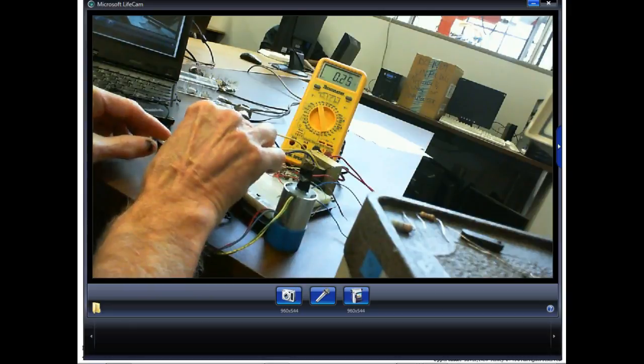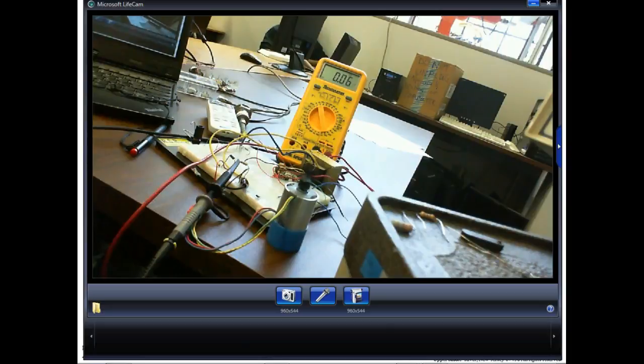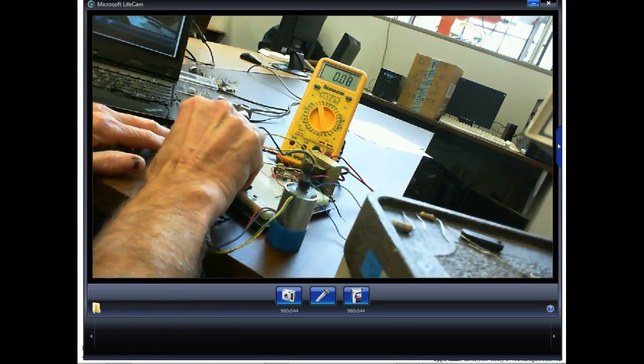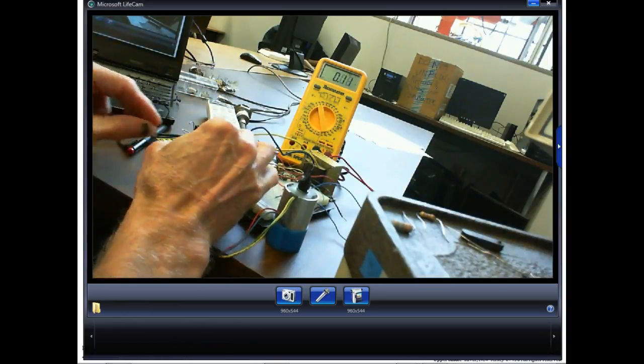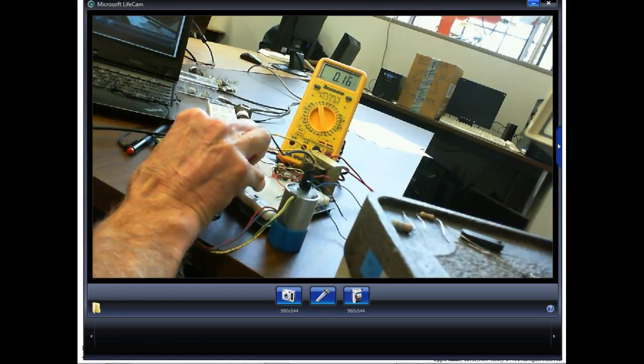I put it across my little DC power supply. Works great. You know, DC motors don't care if it's pulsating DC. Electronics wouldn't like it, but DC motors don't care. So we do this a lot to run motors. All we need to do is make sure we get the right voltage out to run the motor. What would happen if I put my motor across AC? Well, it's not going to run. It's going to sit there and try to vibrate back and forth. You'll see it. Can you hear it? It's a DC motor. It's not going to run on AC.